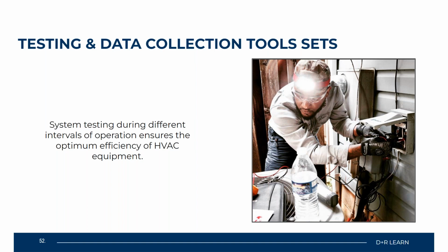I think we touched on this on Tuesday about having logs, either manual or hard copy versions, located in every mechanical plant, electrical plant, and mechanical room. This is important so that we have any type of historical records required to review past operation, either for audits or if we're looking to identify some issue that happens at an irregular interval.